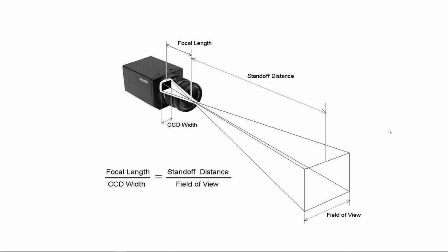And finally, the field of view is going to be the area where the camera is going to see the part. We need to adjust the field of view in such a way that the image is going to be in focus. If we know that the part is going to be moved around, we need to consider all the area where the part is going to be possibly located and add about 10 to 20% more of the distance to calculate the field of view.